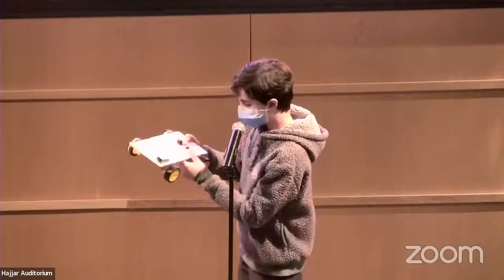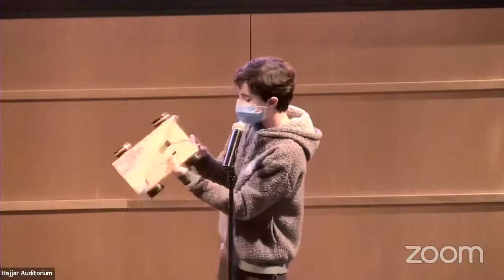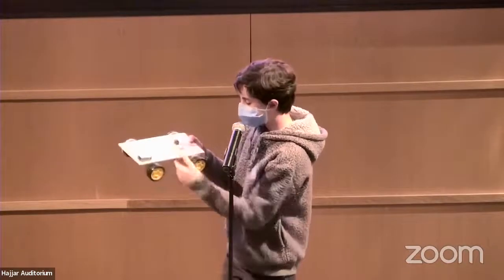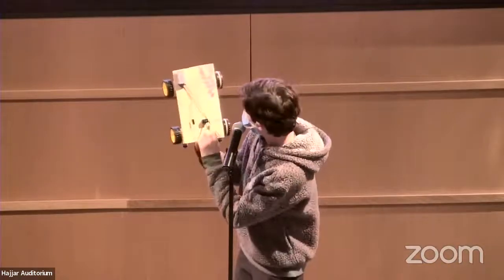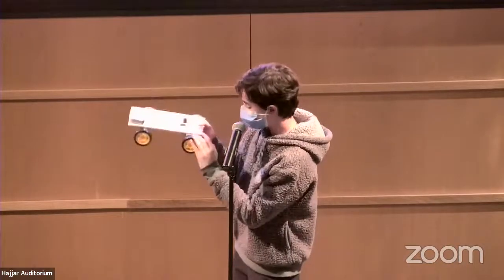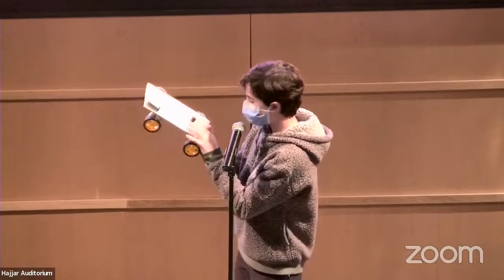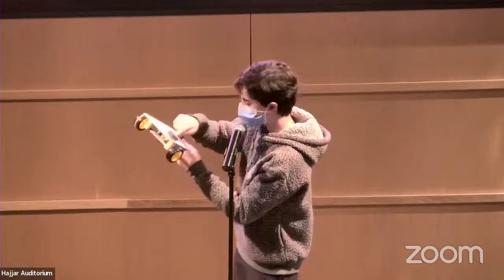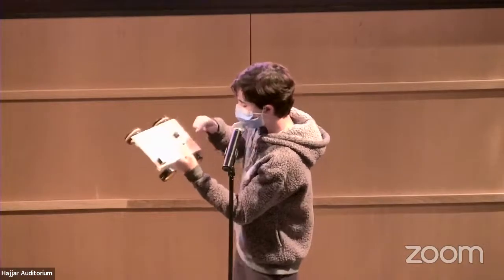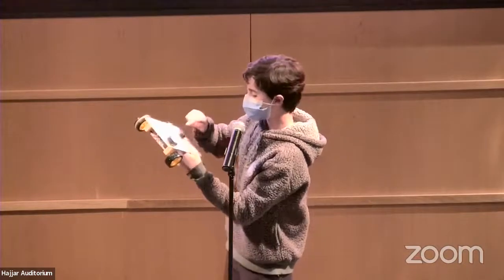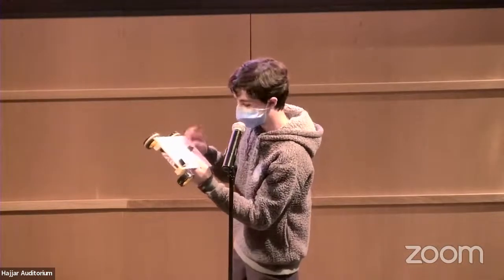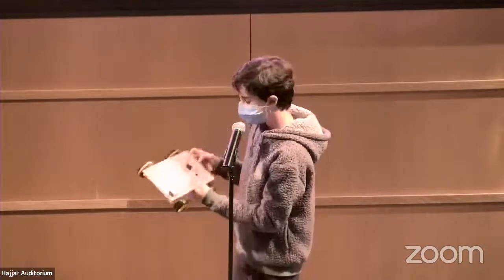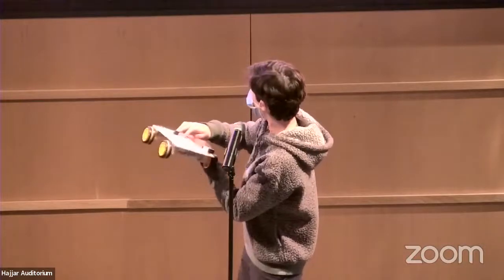So that's what I did for the wires, and I soldered the wire to the motors. After that, I took two more wires, and you can see them right there. I soldered them onto each motor, and I connected them to the switch. So now since everything is connected, I have one wire going to the motor, another wire going to the switch, one wire going from the switch to the motor, and one wire from that motor going back to the battery. So everything can circulate. So when I click the switch, the wheels turn.